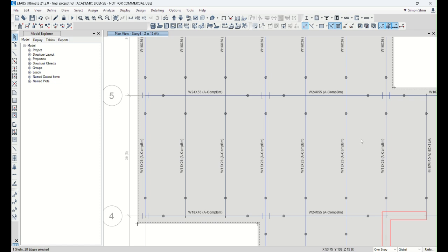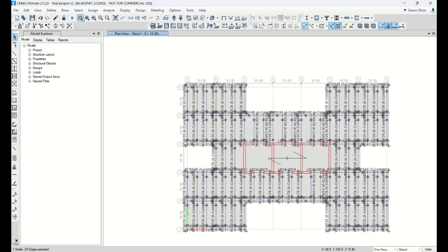Then you need to pay attention and check what moment and shear ETABS used. So basically this is a checking procedure to validate, and then you could do it by yourself. So always be curious and ask, if something is wrong or a weird output: ask yourself, check the unit and geometry, right? That's the bottom line. No matter what, you should do it entirely.